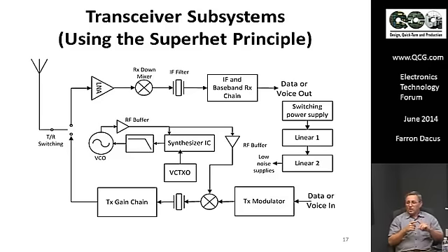Now then, there's two ways that can improve this capability seemingly when people say they're going to the theoretical floor. One is that you need a certain amount of signal-to-noise ratio to demodulate. Now it's typically 10 or 11 dB. But through error correction, there are modern error correction techniques that reduce that quite a bit. Maybe 4 or 5 dB. You get down to 6 dB or so being the required signal-to-noise ratio to get a good bit error rate.